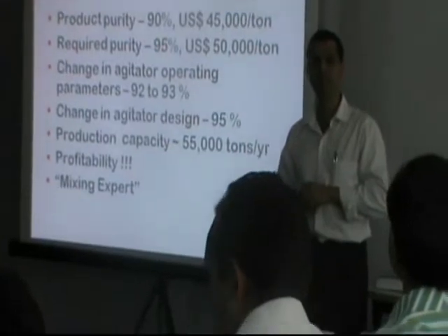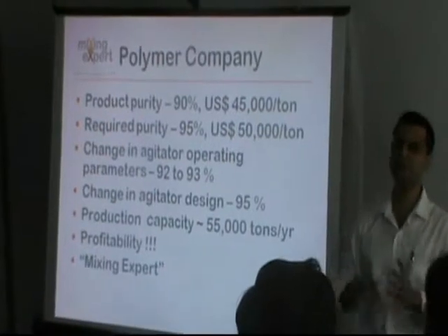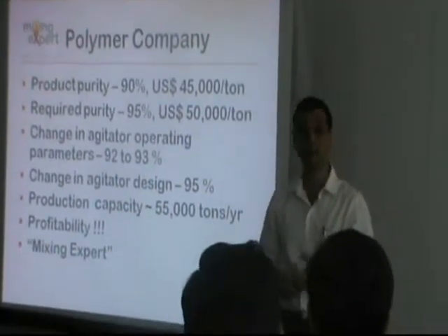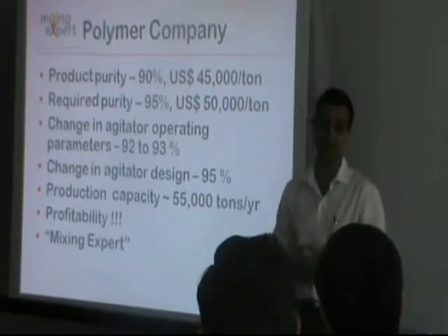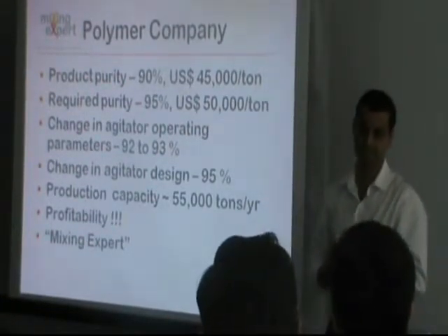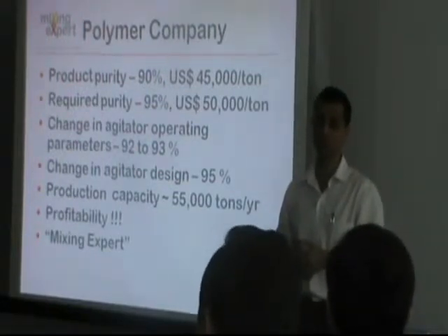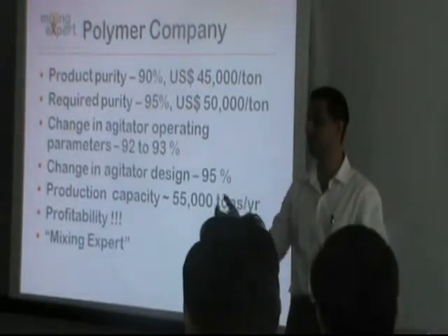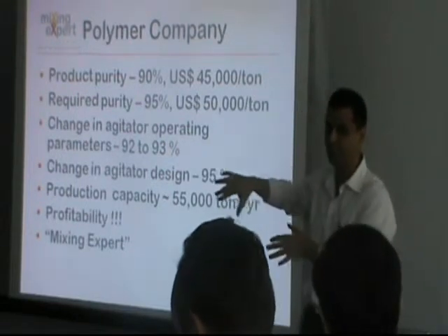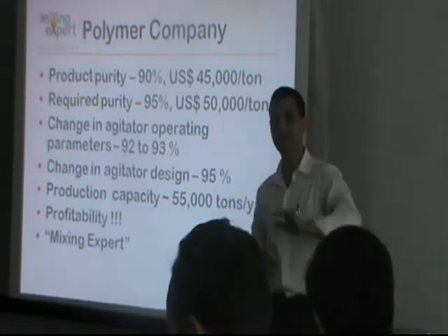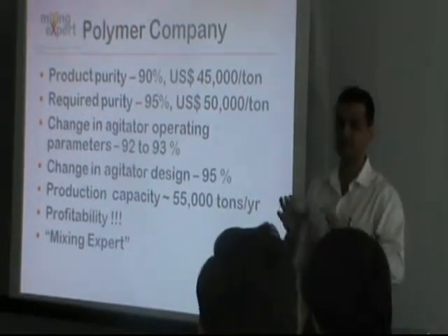Somewhere it's not beneficial. See, in most of the cases, vortex is undesirable, because basically air is getting drawn into the process. But yes, there are certain applications where it is required. Does it help to make a homogeneous mixing? No, because your entire flow pattern gets disturbed as air gets drawn into the system. We would come into that as we move forward, but in most cases, vortex is undesirable. It has to be controlled. That is done by installation of baffles.